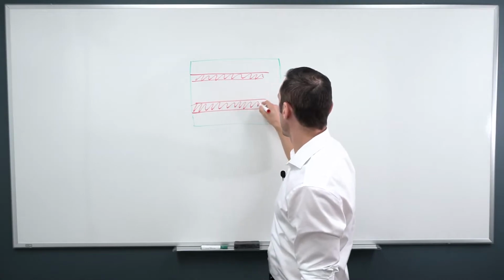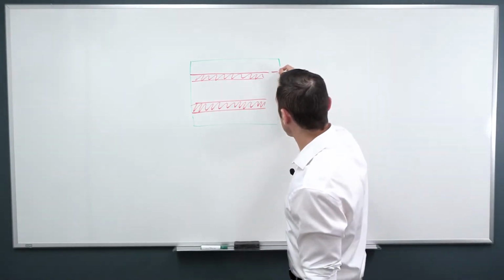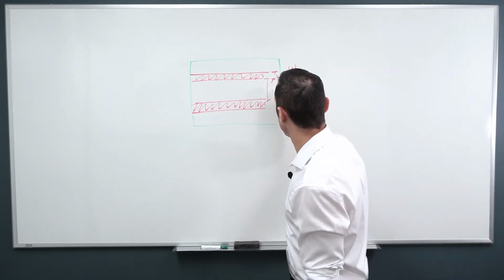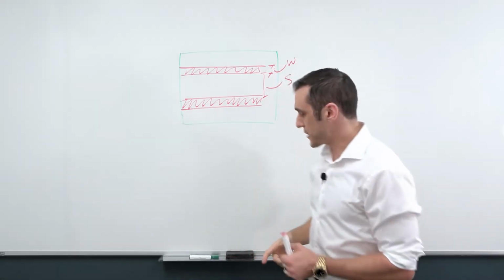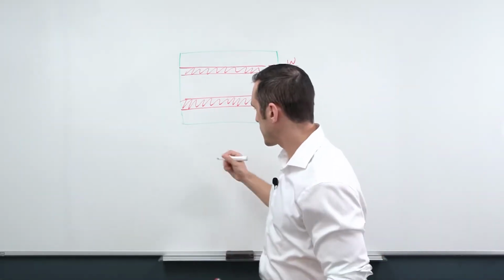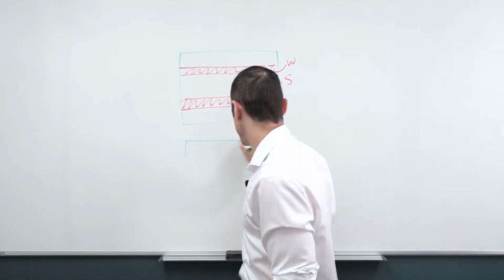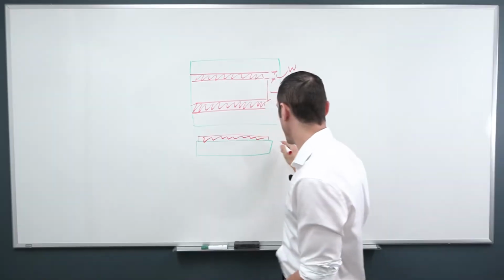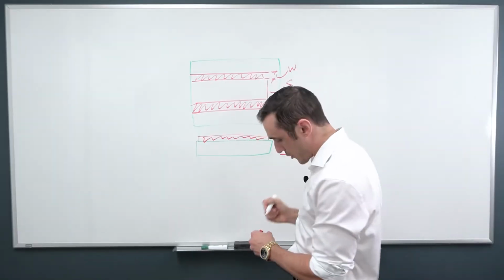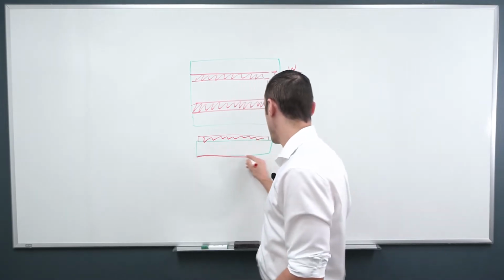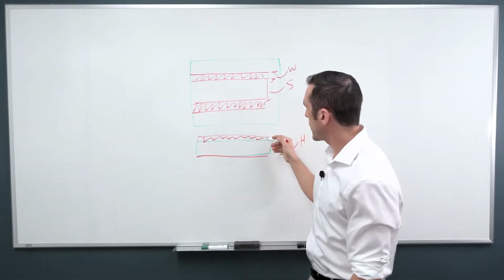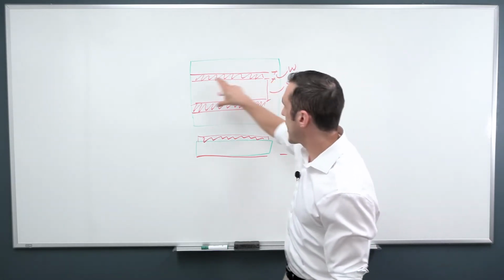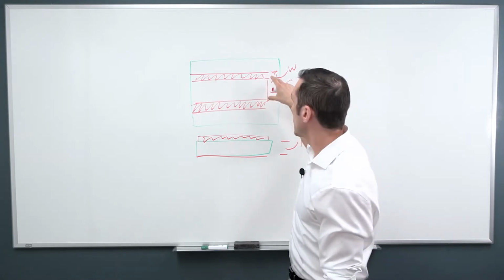And differential pairs are put into a PCB to have a very specific width, W, and spacing, S. And there's actually a third parameter that you need. The third parameter that you need to define in your PCB, so I'm going to show the side view here, is a distance, H, above the ground plane. So here's my height above some ground plane, and I've got ground down here. Here's my side view with my traces. Here's my top view with my two traces right next to each other. So the two of these together, routed side by side like this in parallel, forms a differential pair.